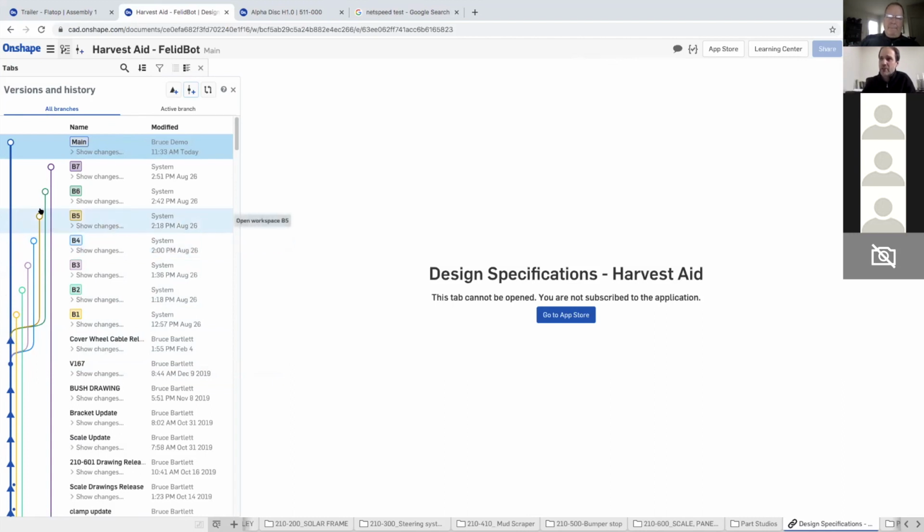I haven't done it on this document, but you can version your branch and then prune it. What tends to happen is you can accidentally get on a branch and start working away thinking you're on the main, and all of a sudden you've got all this work and somebody else working on the main, and you can't get it back together. I'll prune them too, meaning, hey, this was a bad idea, just don't go on with that. You can always reactivate them.